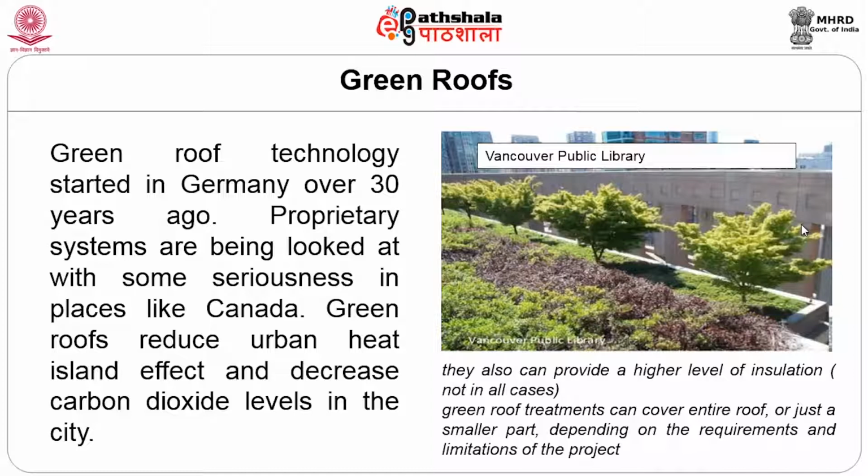So it's a completely green roof, and if you actually come down to the ground floor of the apartment complex, it's like staying at a lawn level of any other ground floor apartment. We are already about 5 floors above the ground, and the terrace has been very cleanly and neatly modified into a green roof. So there are very few successful examples of green roofs emerging in our country, but again, suitable to our climate, this would be one of the best examples to follow, because by having a green roof, we are reducing the amount of heat entering the building through the roof.